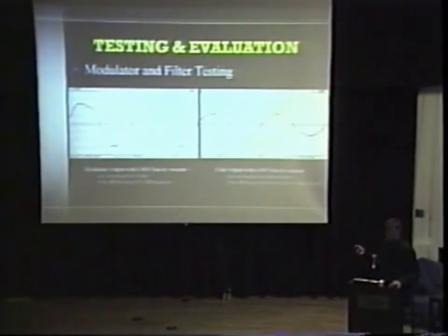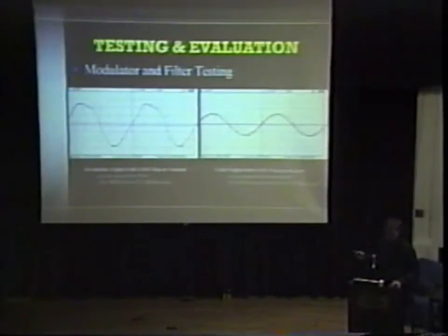As you can see, there's a high frequency component to the waveform. At 4.06, the frequency was successfully 190.5 kilohertz, and after the filter, all out-of-band frequencies have been removed and remains 190.5 kilohertz. Similarly, it was done for the 210 kilohertz waveforms.